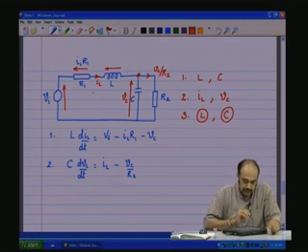Now, apply KVL for this loop. You will get the dynamic equation, one dynamic equation corresponding to that particular energy storing element. Then choose the other energy storing element, in this case it is the C, and here as it is connected to the node, you apply the KCL, because C dVc by dt is going to be equal to the currents through the capacitance.